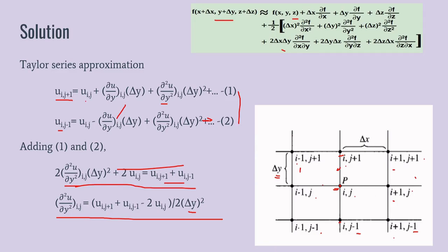Those small cells are not points. Spatially, I am calling it i and j. So it is not the vector denomination, ijk coordinates in the vector. These are the denomination for spatial points. Suppose I have a rectangular duct, and I am dividing this space into smaller regions. This thing is called meshing or discretization.